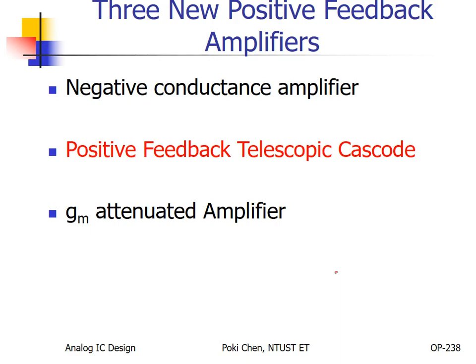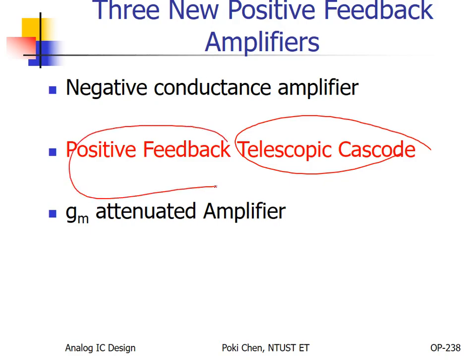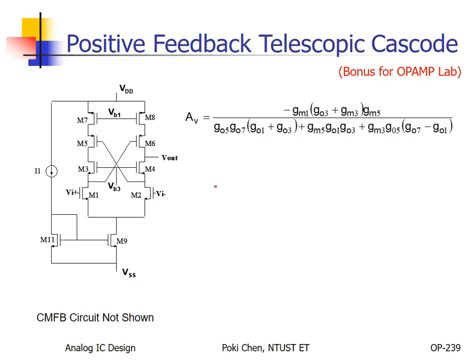And then for the second test chip, I think it is even better. It is the so-called modified telescopic cascode op-amp with positive feedback, to achieve even better performance without any kind of tuning. You can see this. What is the original telescopic cascode op-amp? If you remove the cross connection, then you apply some kind of fixed bias here. That is the original one.